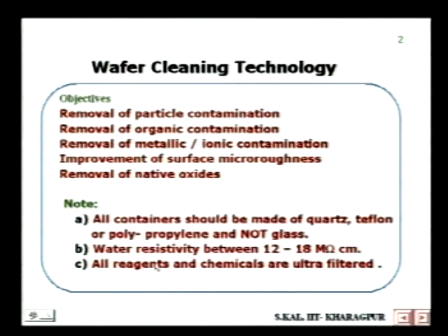All reagents or chemicals used for cleaning the silicon wafers are ultra pure and ultra filtered. The chemical grade for processing VLSI chips is VLSI grade, which means the impurities should be as minimal as possible. That grade is sometimes known as MOS grade, electronic grade, or semiconductor grade chemicals.